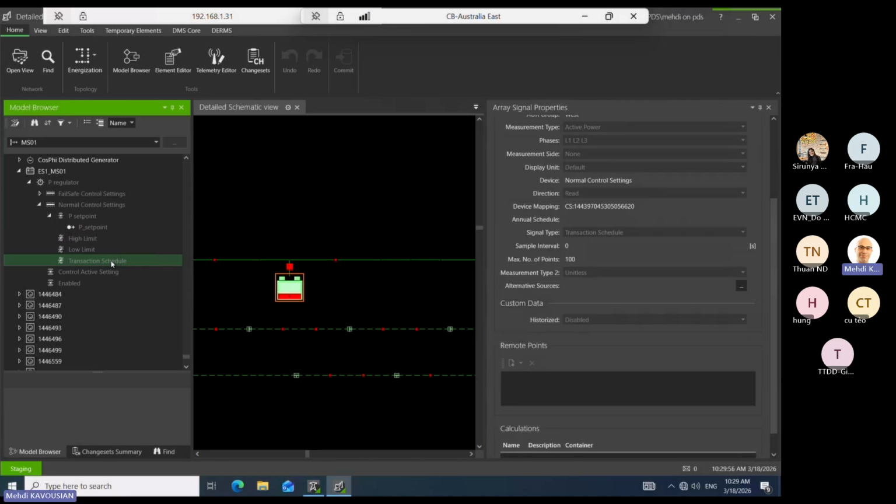But how could we send the schedule to the real devices? Oh, you're thinking of, okay, SCADA has an ID. Yeah, got you. So the set point is SCADA, okay, so it's DNP3 or ICCP, up here. These are sent by interface IEEE 2030.5. And for that IEEE 2030.5, there is some key for the transaction and that data will be sent through that.